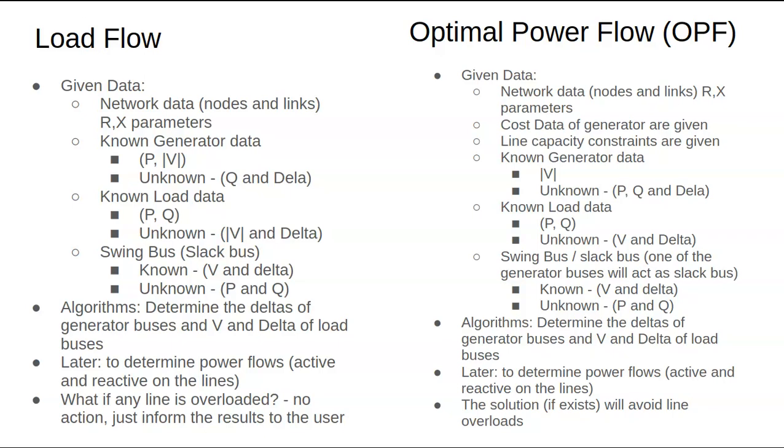Then when you do load flow, what I told is unit commitment, and after that, optimal power flow. Then when do you need a load flow? For planning scenarios also we need it, sir, if I am going to construct new transmission lines, or if a new generator is commencing, for an addition. See, in a way, optimal power flow is more calculation based and intensive. Let's say there's a generator. Optimal power flow is saying that the generator capacity is 400, but it should generate only 250.